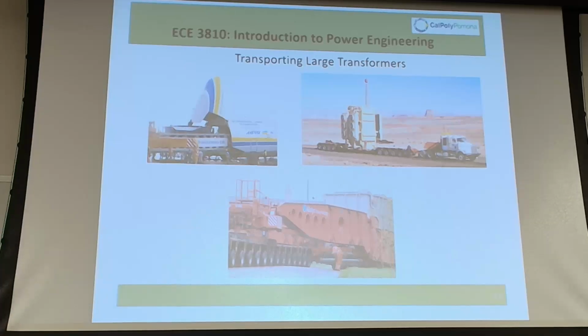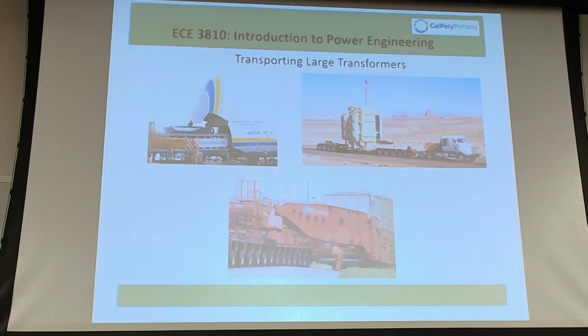So moving these pieces of equipment, like I said, it has a bunch of things. It has accelerometers and sensors, so if the transformer tilts too much while they're moving it, the utility will say no. Because when you move it, you can shift the core or the light parts inside the tank. That's what they pay a lot for.